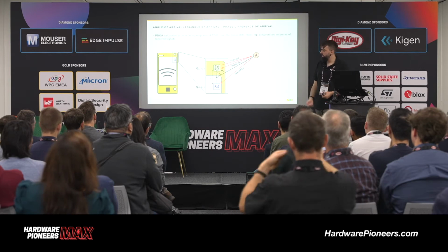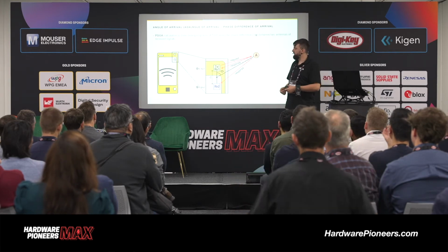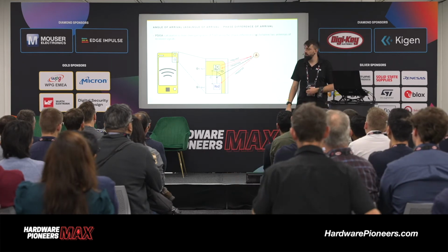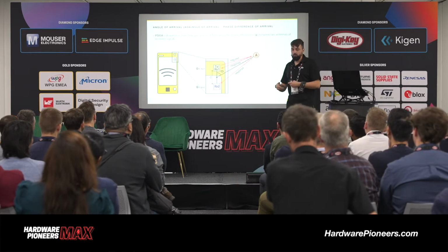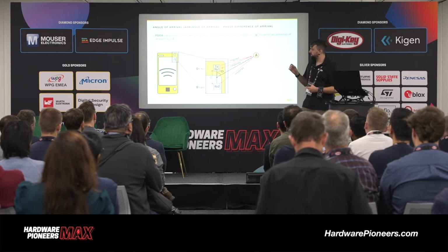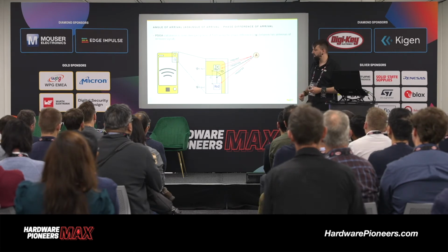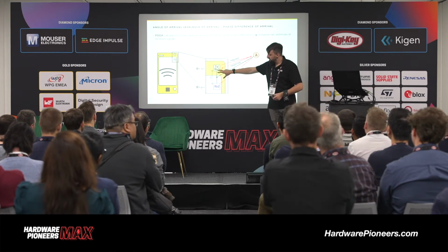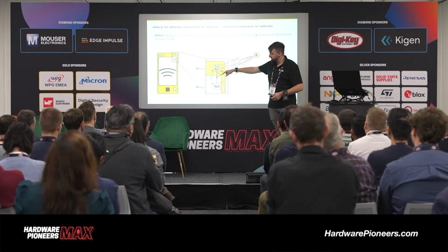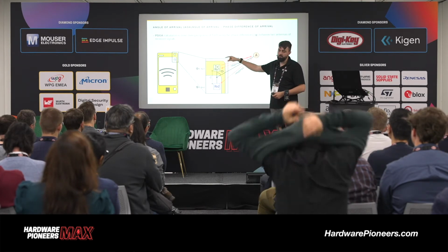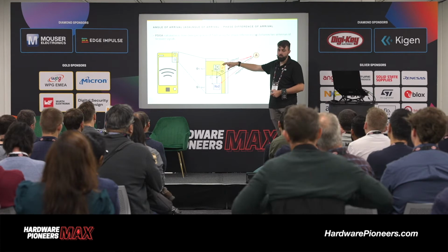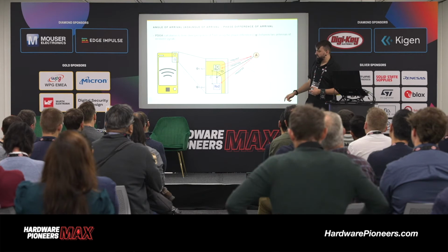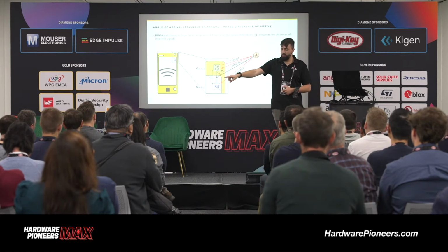The fourth thing I want to show you is the phase difference of arrival. It's PDOA. It's similar to TDOA, so time difference of arrival, but with phase difference of arrival, you measure the incoming angle of the ultra-wideband signal between two antennas, and from this phase angle, you can measure the angle of the received signal, which is one thing enabling the Follow Me rover.